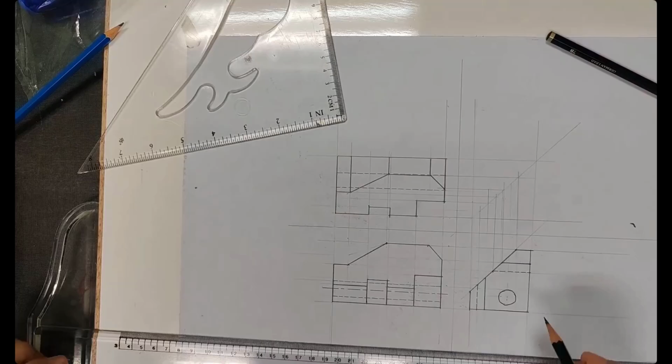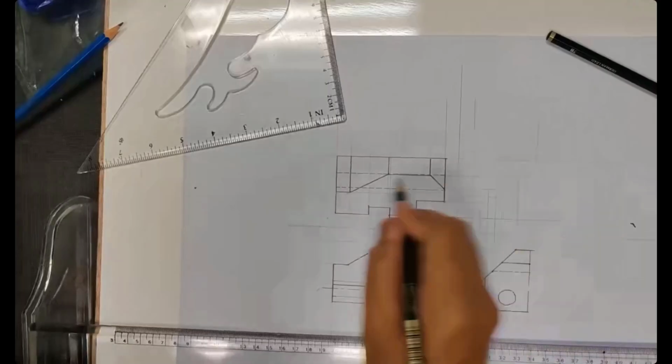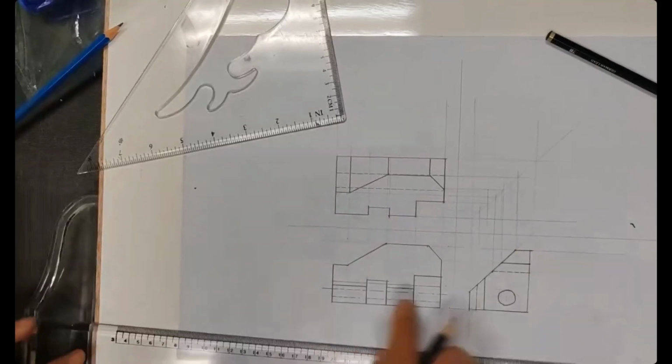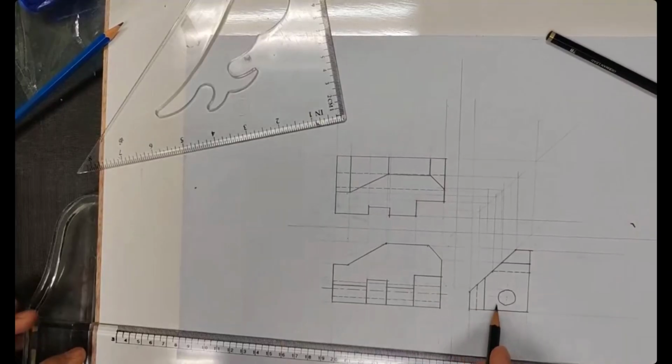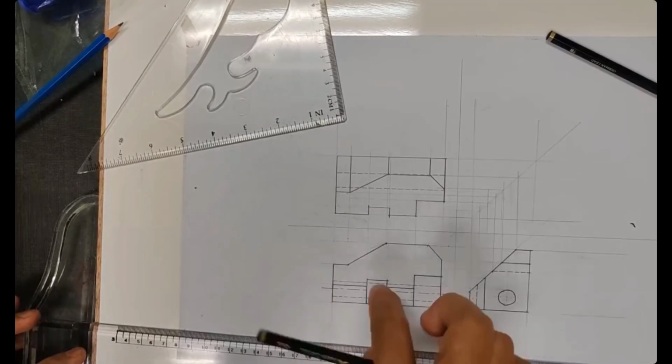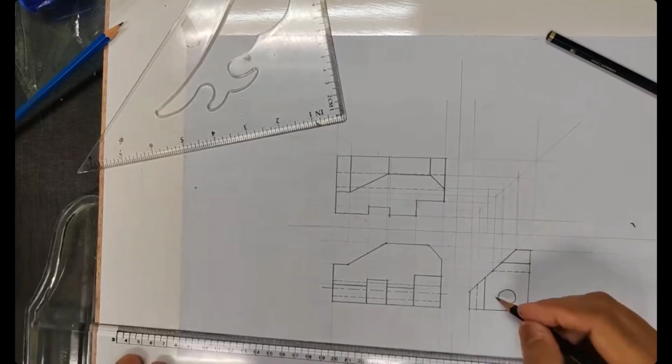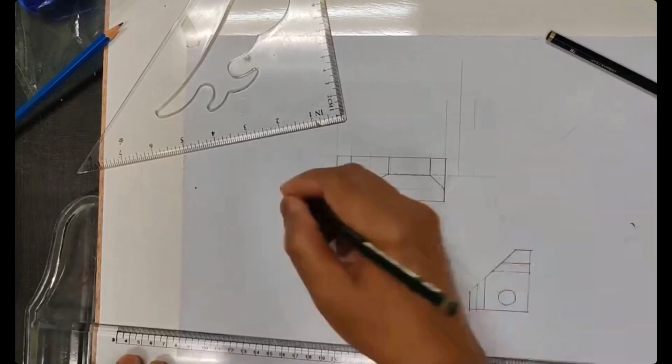I didn't bring my compass, so I draw by hand. I bring all the quadrants here, 45 degrees, bring it there. Here also I bring it to the front view. Can you see I bring all the quadrants of the hole? I draw it on the side view using a compass. You must use a compass. Bring the extension line, then I make the line. And the center line, can you see it is passing through the edge? The axis of the hole from the front view does not stop at the edges. You must cut through the object, as shown. Same goes here, the quadrant of a circle, bring it there.